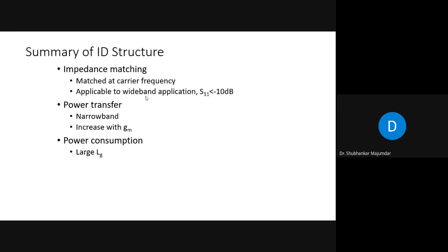At that time, the impact of frequency, which is XL equal to omega L, is very less, because the inductor is working as a resistive load at that S parameter, when the reflection is very less. Reflection very less means you have a matched circuit. Then only this reflection will come very less. When we are purchasing some RF instrument, we just check that the reflection should be less than minus 10 dB.